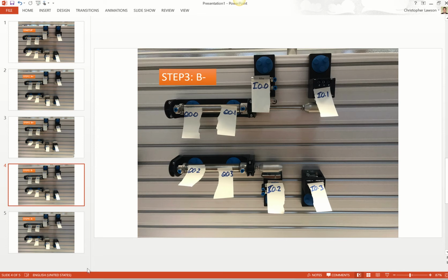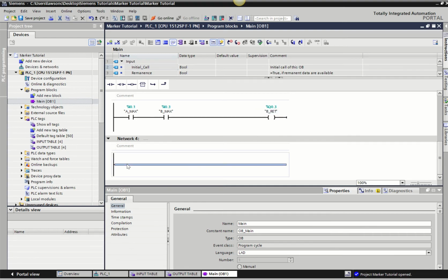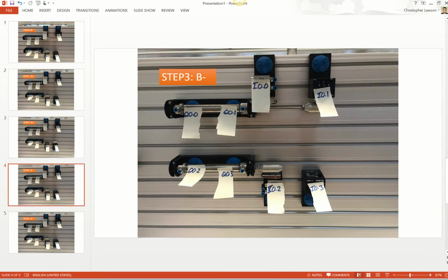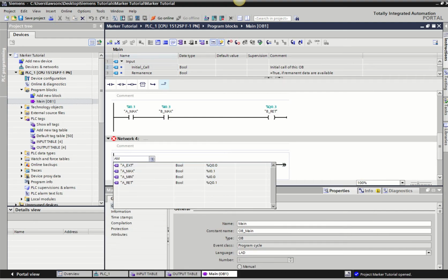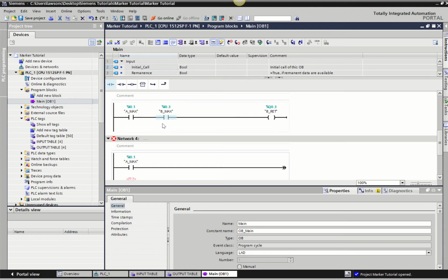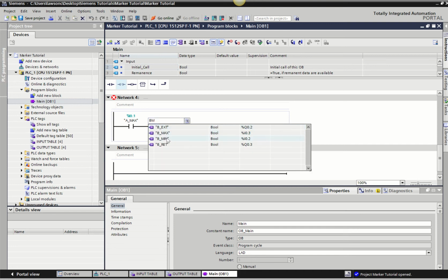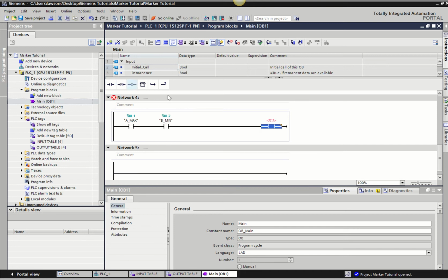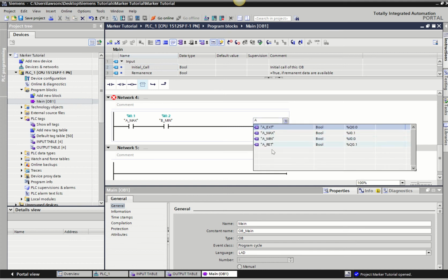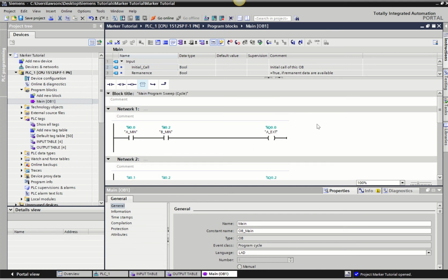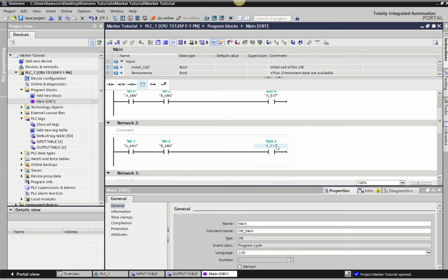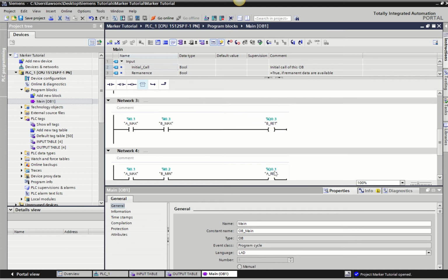These two inputs are triggered, which will then allow us to put A back. So what we have here in this setup is A max still triggered. We're now B min. Sorry about that. And then that's to ultimately tell us A to return home. And that's essentially our sequence: A extends, B extends, B retracts, and then A retracts.